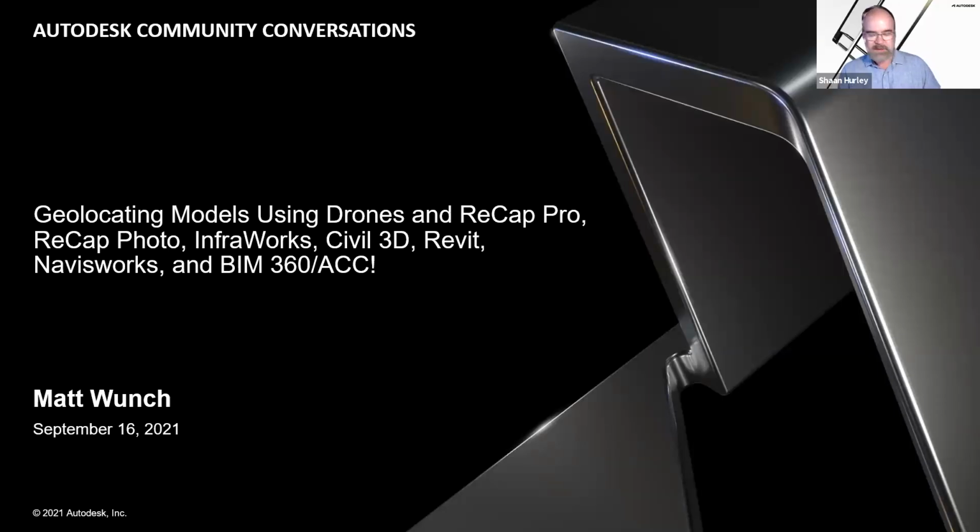So I am going to go out and grab, in this case, my connected BIM 2022 SQLite file. This is a brand new drawing in Civil 3D, never been touched, nothing's been done to it. And right off the bat, it says, hey, you don't have a coordinate system set. So let's click that, and yeah, let's use the one in InfraWorks. That's going to set my coordinate system in Civil 3D to match that Connecticut NAD 83 coordinate system. So that's cool, right?